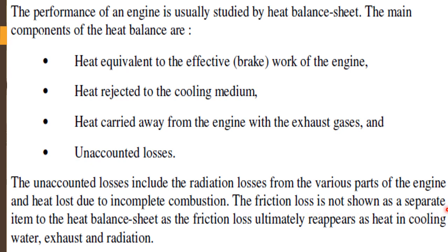The friction loss is not shown separately, because the friction loss ultimately reappears as the heat carried by the cooling water, heat carried by the exhaust gases, plus radiation. So in the heat balance sheet, what we observe is this part: heat equivalent to the brake power, heat rejected by the cooling medium, heat carried by the exhaust gases from the engine, and unaccounted losses.